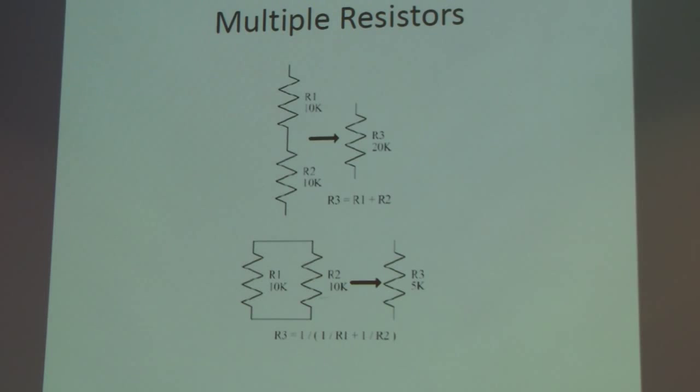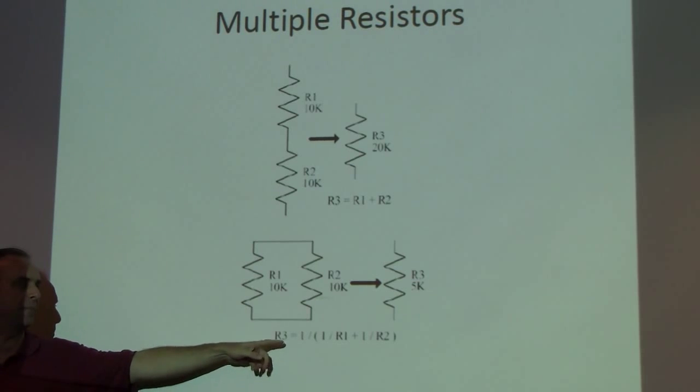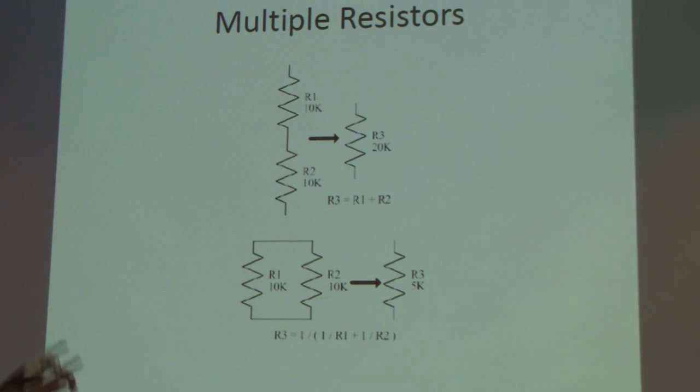Now there's a limit to this statement: at very high frequency, the interplay between the two resistors actually changes slightly. But for the purpose of the discussion with ideal resistors, you can simply add resistors by putting them in series. Likewise, if I put resistors in parallel, I diminish them because I add them by their reciprocal. So these two relationships are fundamental both to synthesize new values and to analyze circuits. And you will see these repeat for both the inductor and the capacitor in a minute.